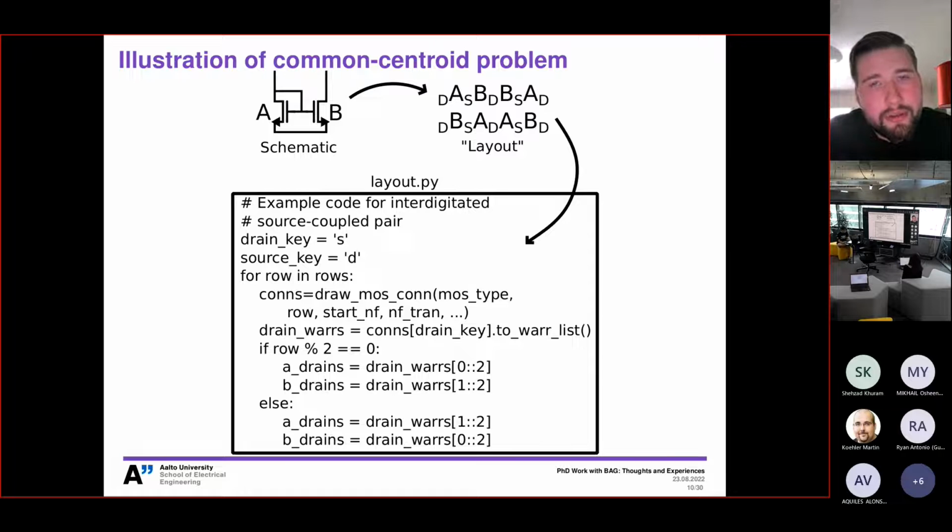And then of course, depending on the number of dummies you have on each side, you may have to fix the schematic generation if the dummy terminal labels are not correct. So you may have to take care of that, but that is also relatively simple to achieve.